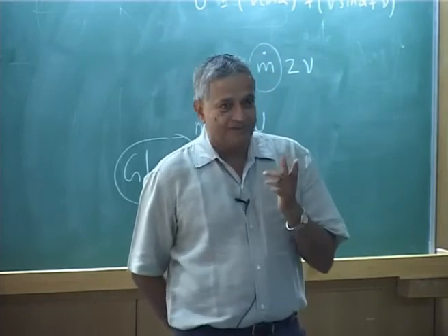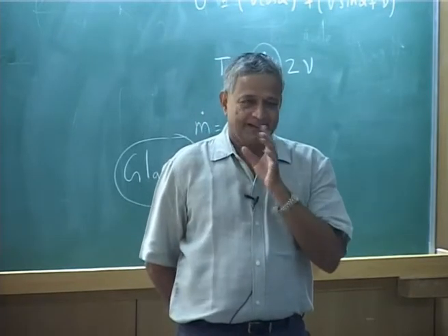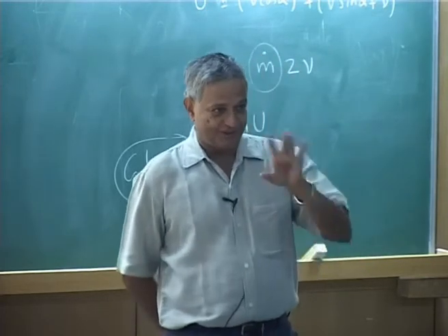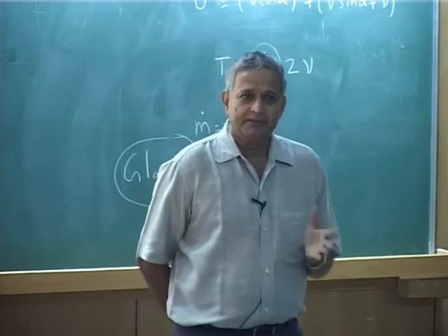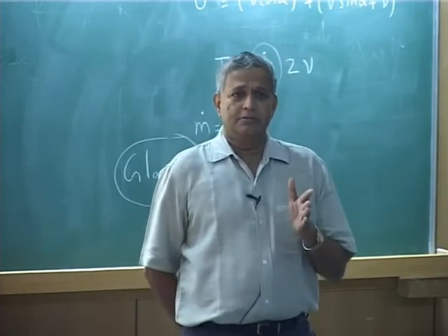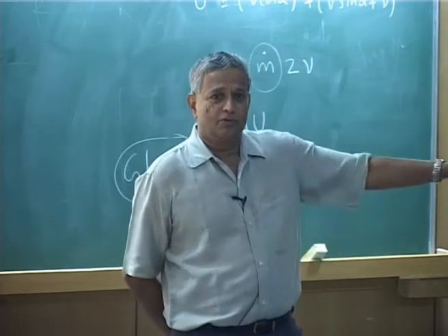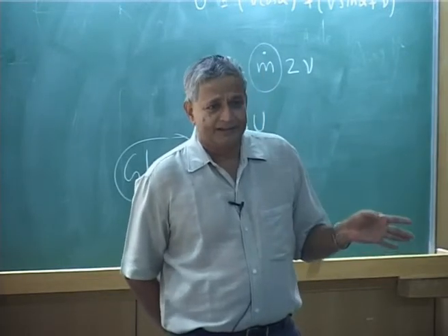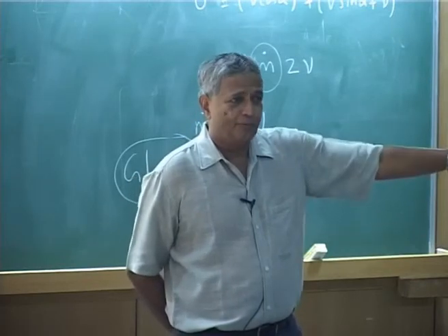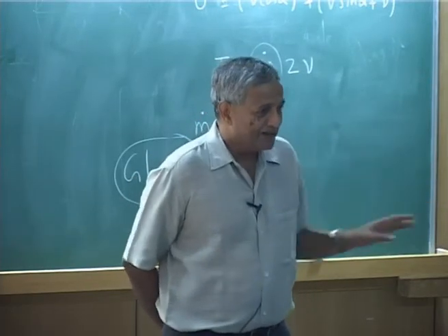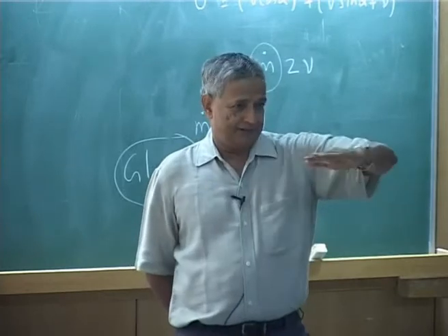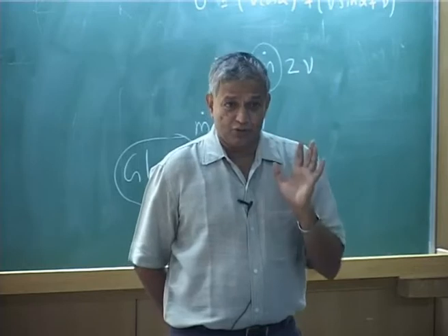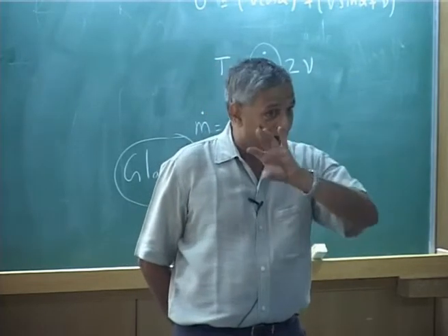In the high speed flight, I have to get an expression. Please understand, this is how the whole logic goes. For the lift, we should look, because you know from the lifting line theory for an elliptic wing, in a horizontal flight, you get the lift and the induced drag expressions. That is how it was brought in.